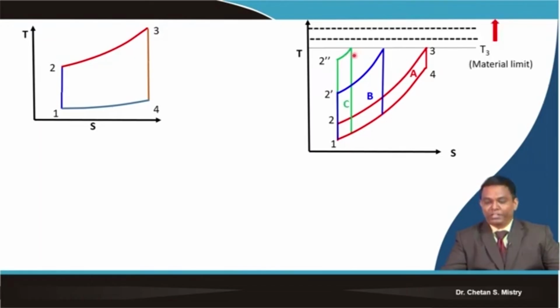Over time, people have been looking for increased efficiency of the gas turbine cycle, and this is possible by increasing the turbine entry temperature. This turbine entry temperature has a big limitation for our application, because metallurgical constraints come into the picture. If the temperature is too high, it may burn the gas turbine blades. This is also one of the major areas of research these days. People are talking about blade cooling technologies.